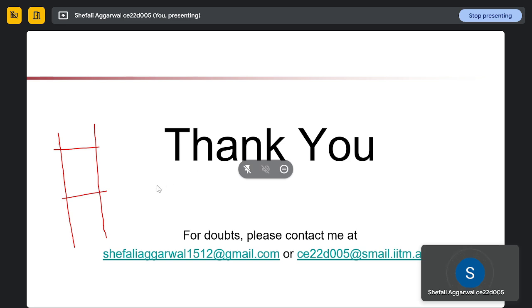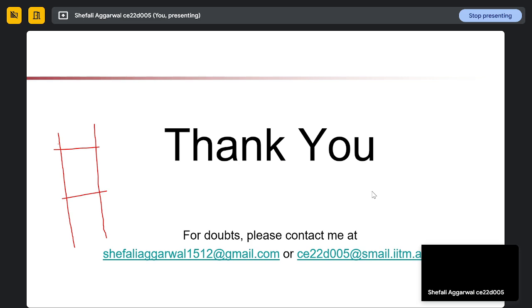Lacing is generally given only for a column with built-up sections. If you are using a single I section, you will never find a lacing system. If you have two I sections in a single column, you are making a built-up section. Then only it is called lacing. Lacing is provided only in built-up columns. And where are bracings provided, sir?